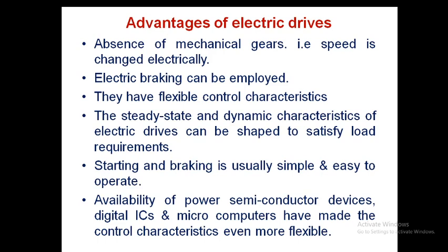And the next one is that the steady state and dynamic characteristics of electric drives can be shaped to satisfy load requirements. Loads here may be fans, pumps, washing machines or air conditioners. To satisfy that load, what is the requirement? Speed-torque characteristics. We can shape the speed-torque characteristics, both steady state as well as dynamic, as per the requirement of the load.